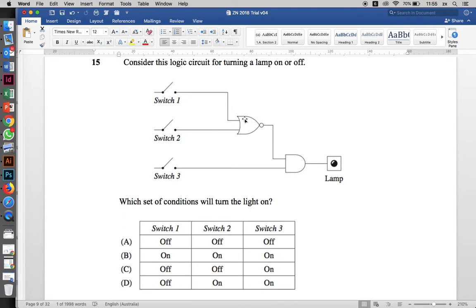So that means if it was an OR gate, that would say if either of them are on, the whole thing is on. So in this case, they're both on. So because they're both on, that means this thing's on. The NOR gate flips it, and now that's off. Okay, so we have an AND gate, and the AND gate says, well, these both need to be on to turn the lamp on. So this one's already on. Where if we have both of these off, we get something that's on. So this one's off. We have on and off. On and off is not enough for it to go on. They both need to be on. We only have one on. It's only 1 out of 2.